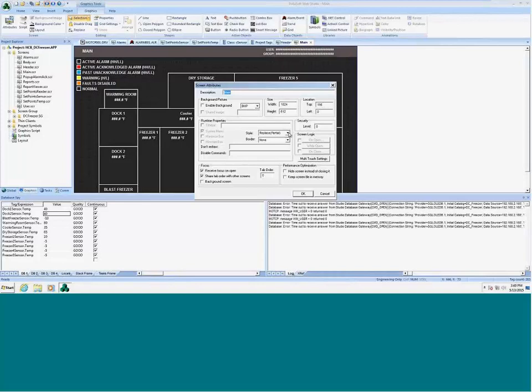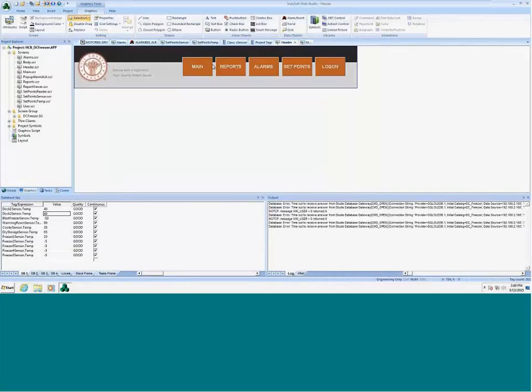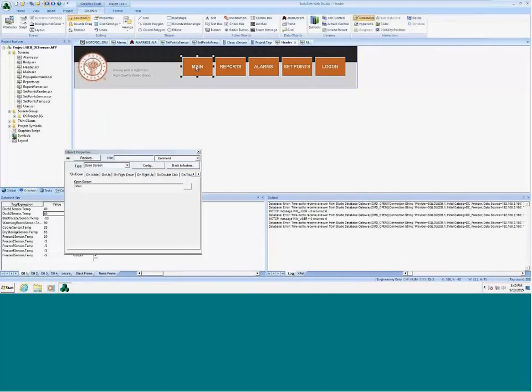This replace partial style, as opposed to the pop-up that he mentioned before, is a property that simplifies your changing of screens. Rather than having to open and close a different screen, you just open a screen, and if anything covers the screen partially, the screen will close out. So if you look in the header, as he pointed out before, I'm simply doing an open screen function for the command.